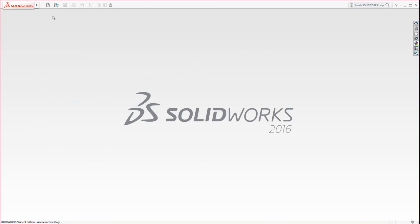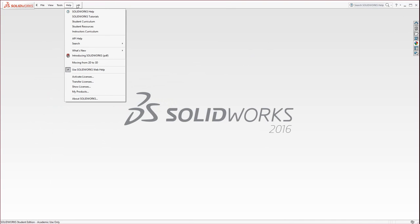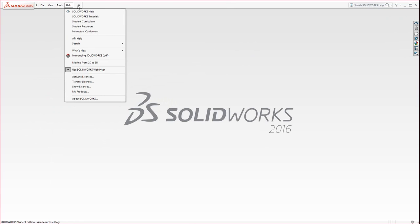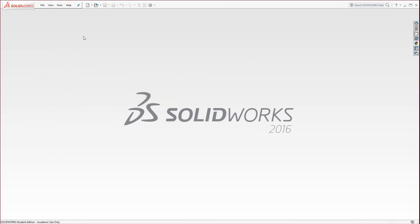When you start up SolidWorks, just make sure you go up here. I like to have this tacked on. This little arrow, if you move your pointer over it, you'll see pull-down menus appear. I like to turn that on because I like to show both pull-down menus as well as the icons. And I'll show you some fast keys as well.